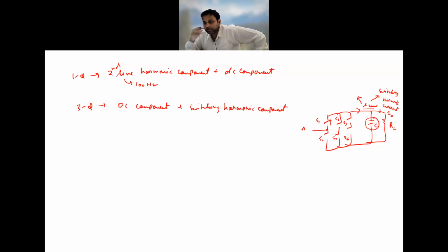See, that is what we have done. We have calculated the RMS in one switching cycle, and then we have calculated the RMS in the entire line cycle. However, if you see the RMS value of the current which is going through the capacitor, IC RMS, is independent of the switching frequency. See, RMS component is what? It is a kind of a mean, square of the means what we are taking. So that is independent of switching frequency.